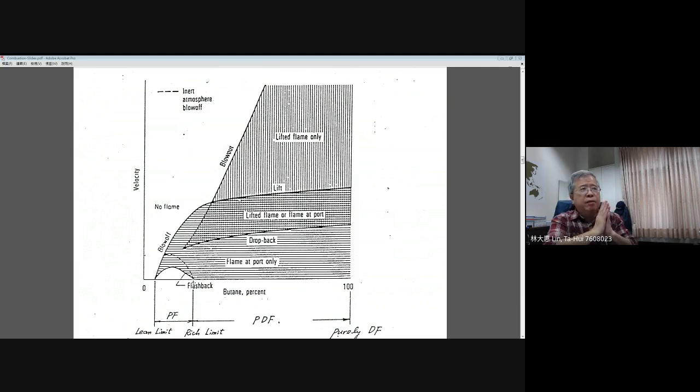When we identify the broken line, it represents that there is no additional oxygen in the downstream environment to give you a possibility to stabilize the diffusion flame, right? And here, this is a rich region. This is a rich region. And here, this is a lean region.